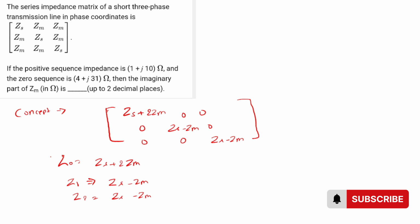In the given data, positive sequence impedance Z1 and zero sequence impedance Z0 are given. So Z0, 4 plus j31, equals Zs plus 2Zm, and positive sequence impedance 1 plus j10 equals Zs minus Zm.